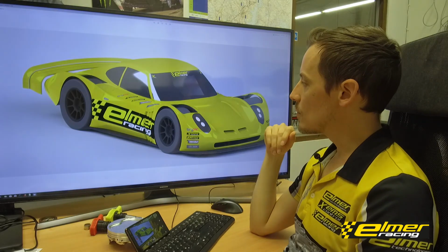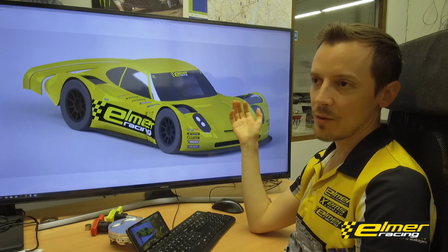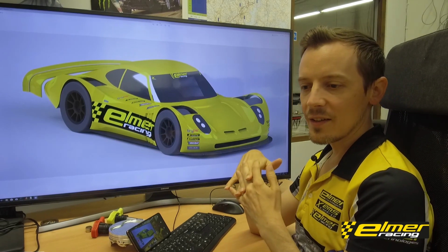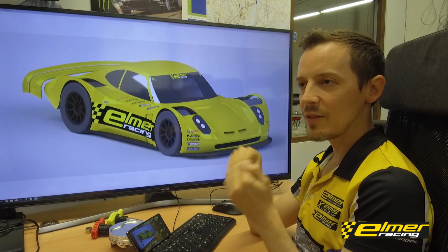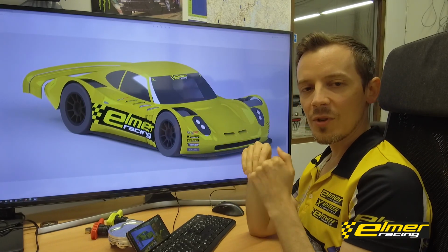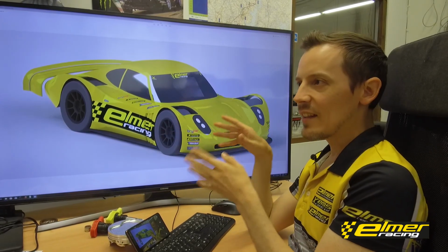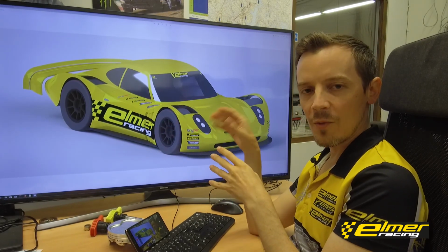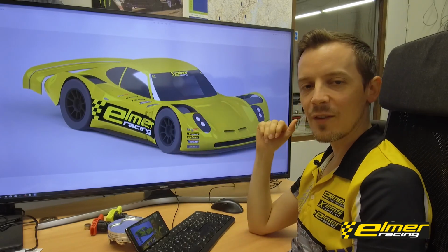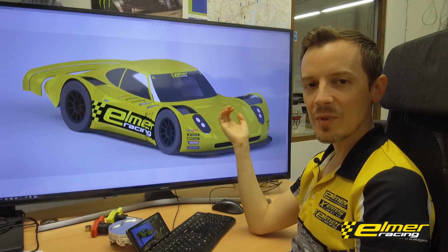But yeah, so those are some of the things that we've been thinking about with this. And of course, with modern CFD you can do so much more innovation and advancements. Of course, you always have to be wary about actually having useful data. If you don't have any tests checking that the results you get from the CFD are meaningful in the real world, then it's easy to get nice color plots and flow lines and all kinds of stuff, but that doesn't really mean anything unless you have some evidence that this is actually how the flow is behaving in the real world.